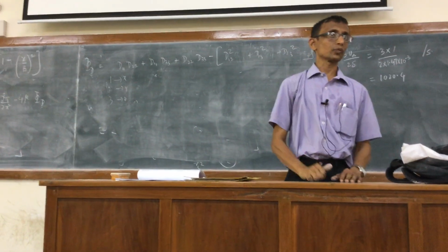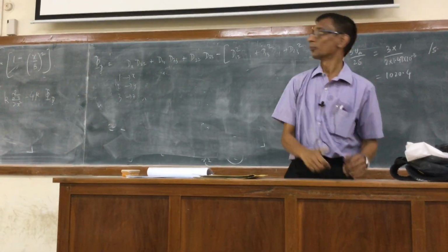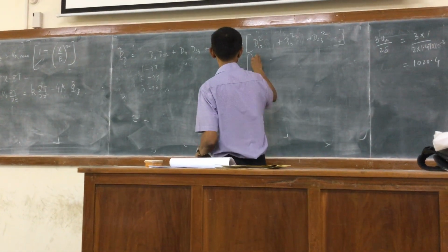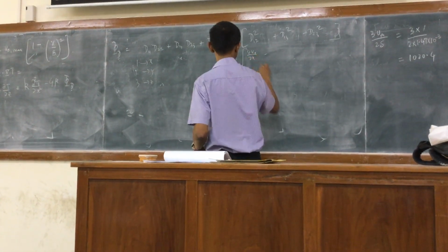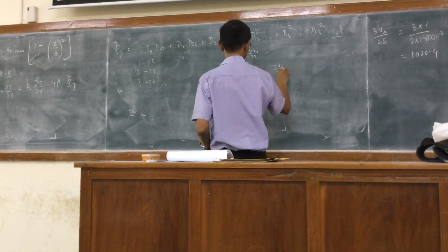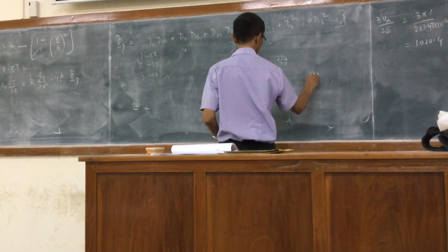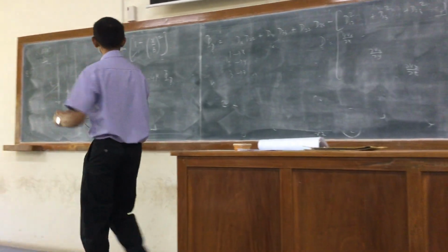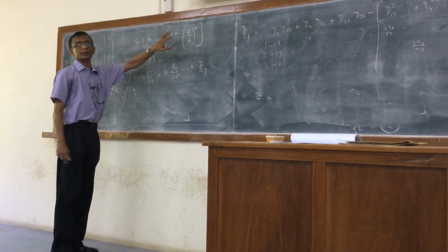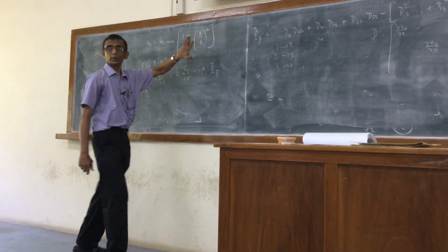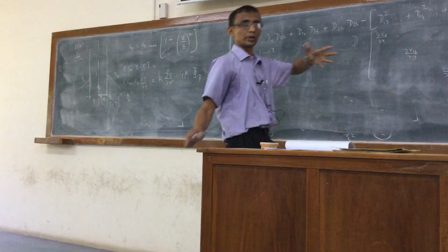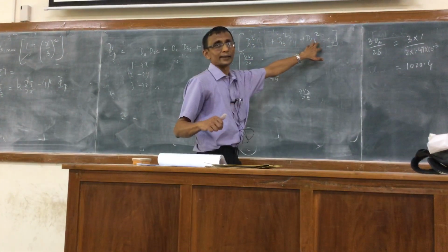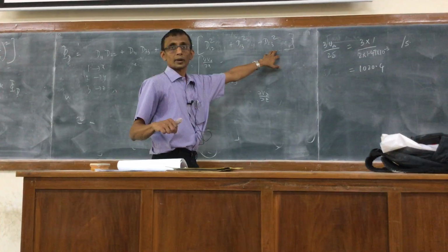It's very easy to write down the formula for D. This would be dvx by dx, and this would be dvy by dy, so that the trace would be the divergence, right? And clearly, you have dvz, and it's a function of x alone, so even looking at it, you can see that only the Dxz is going to come into play.